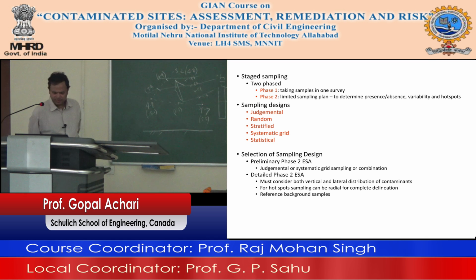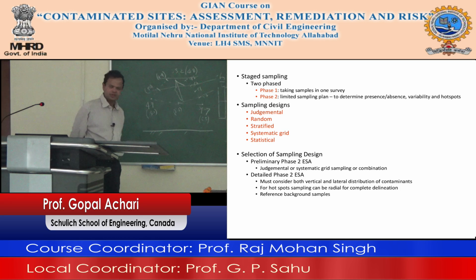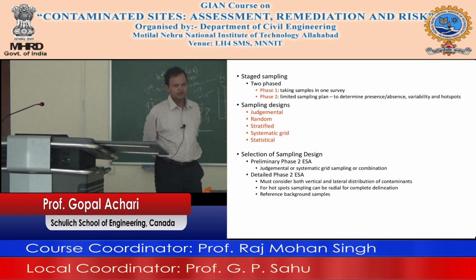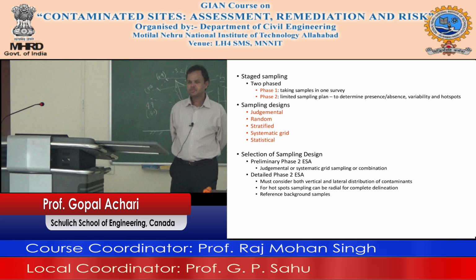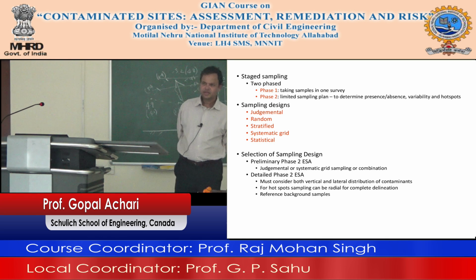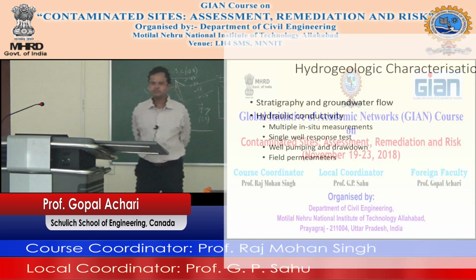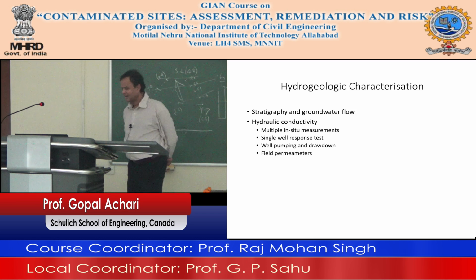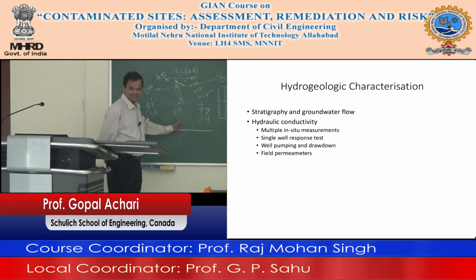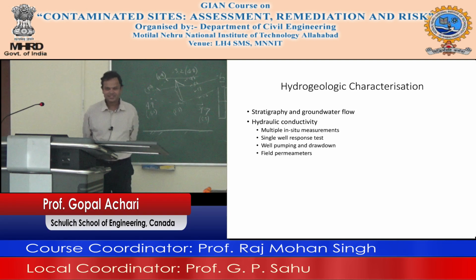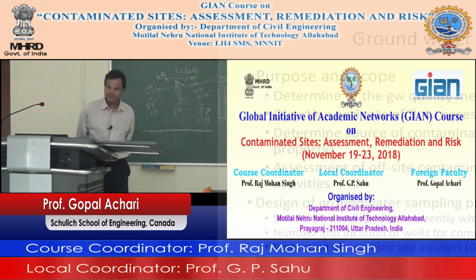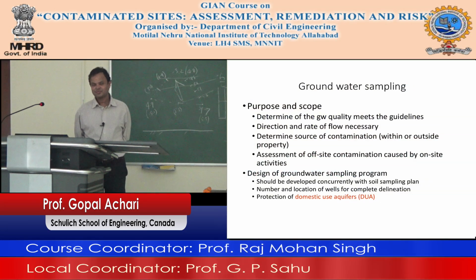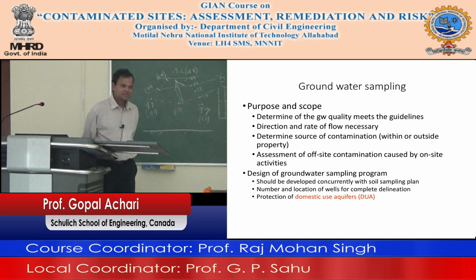So stratigraphy and groundwater flow direction, hydrogeologic characterization. If you're doing sampling of the subsurface, you want to achieve multiple purposes with it. You want to get soil samples, you want to get groundwater samples, you want to actually understand how the groundwater flows, measure the groundwater table, which direction, what is the flow gradient. All that you can capture with the same system that you are going to use for subsurface soil sampling.